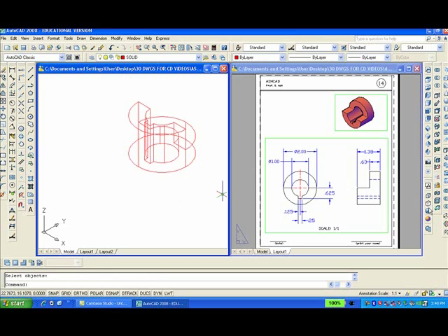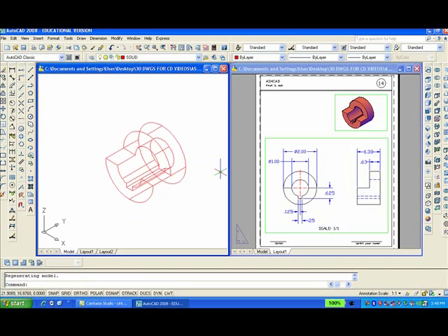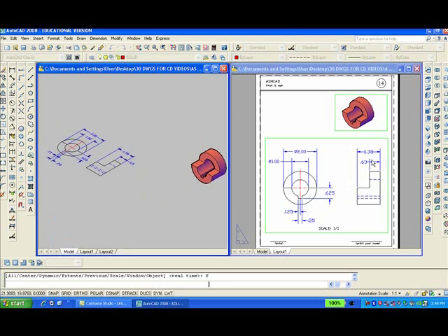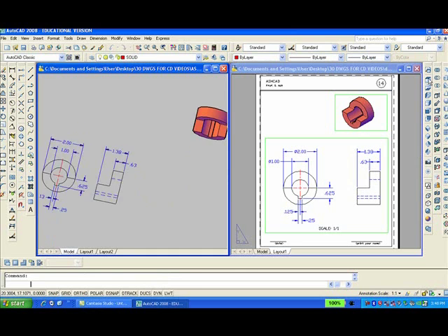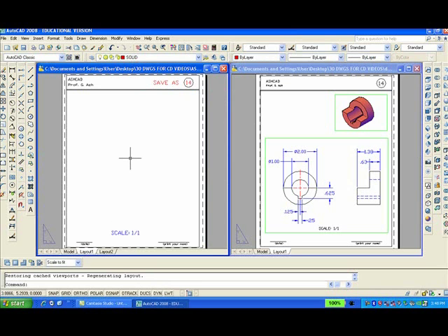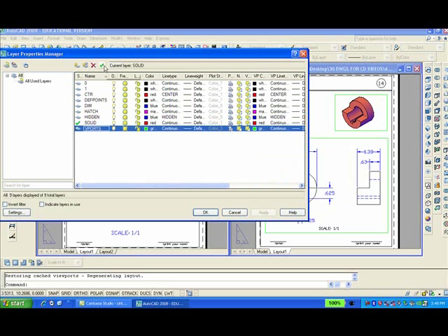And then we're going to have to use a 3D rotate command. Select the object here, and we're going to put that at the center line here. Click on the red axis and type 90. Hopefully it's right. I'll add shading. It looks correct, so I'll Z enter, E enter, move into the top view, switch to layout mode, make layer viewport current,